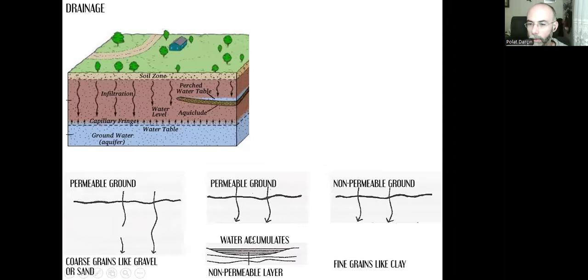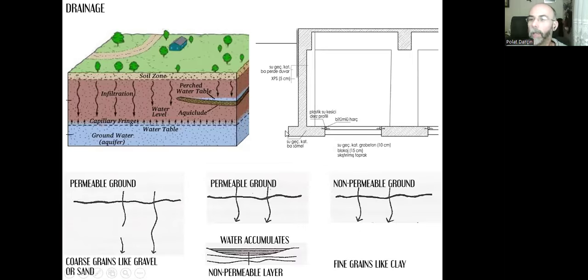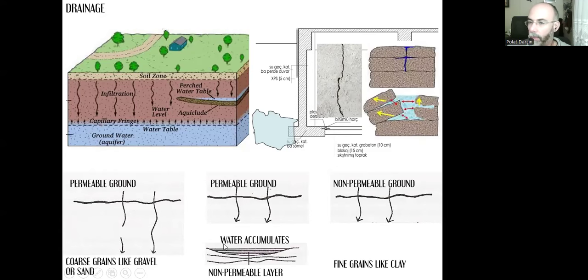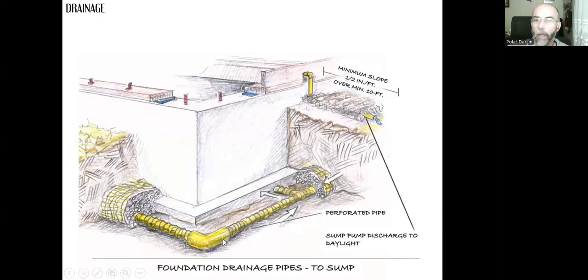In these two circumstances, there can be water next to our footings or raft foundation. And that's something that we don't want. We want to protect the footings and the raft foundation from the water damage. If there are cracks, that water can penetrate inside the basement floor, or it can harm the reinforced concrete and reinforcement bars. If it freezes, it will expand and explode the components.